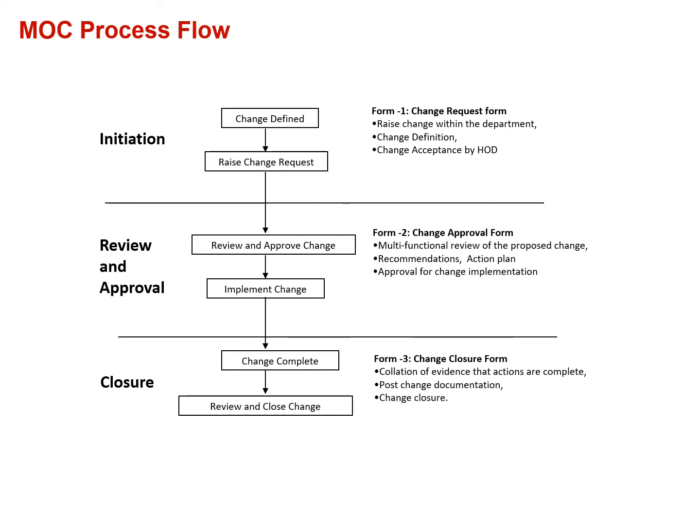MOC has a process flow. Firstly, it should be initiated. Second, the review and approval. And the third and final part is closure. In the initiation step, the change has to be defined and a change request has to be raised, and it should finally be accepted by the HOD of the user department.